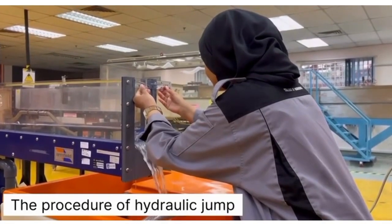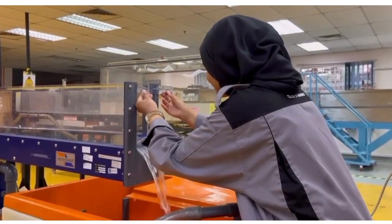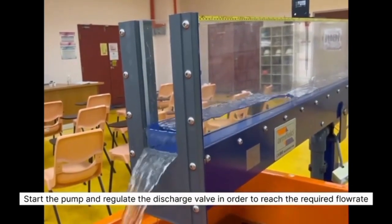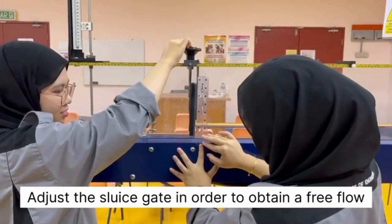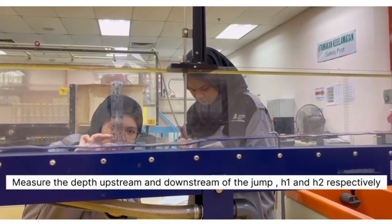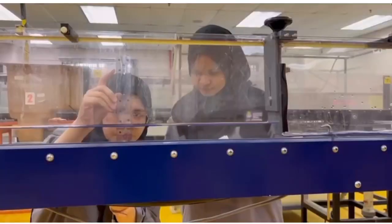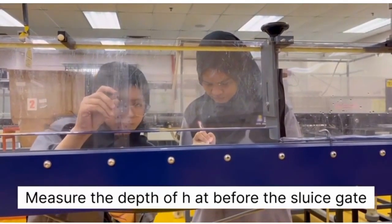The procedure of hydraulic jump. First, we measure the channel width and close the reservoir outlets. Then, start the pump and regulate the discharge valve in order to reach the required flow rate. Adjust the sluice gate in order to obtain a free flow. Measure the depth upstream and downstream of the jump, H1 and H2 respectively. Note down the values. After that, measure the depth H before the sluice gate.